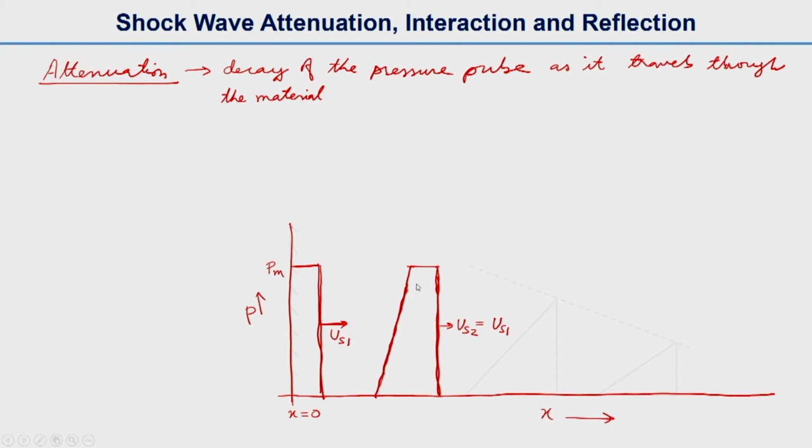This, as you know, comes from the interaction of the release wave. Release wave means the reflected wave that comes back from the back surface of the projectile. So this is the release wave portion. We can have the velocity of the release wave, which we earlier had as c plus up. C is the sound wave velocity at a particular pressure P, and up is the particle velocity.